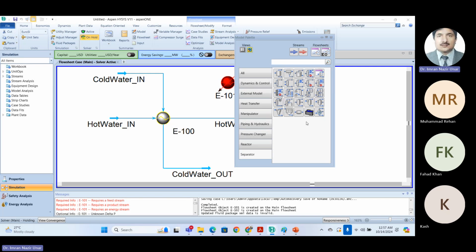But if we have a relative volatility close to 1, it means they cannot be separated on the basis of vapor pressure or boiling point. Distillation is not possible for isotopes, so we need to think about some other operations. Sometimes the relative volatility is greater than 2 or even greater than 3, but it is prohibited to raise the temperature beyond 50 degrees centigrade because the product deteriorates its properties and cannot be used in pharmaceutical products.